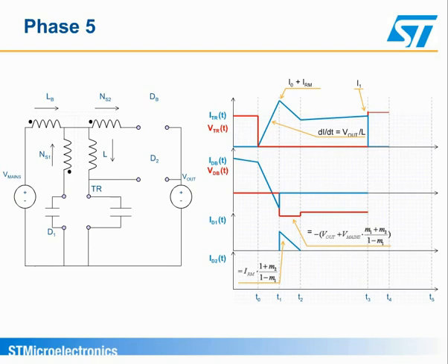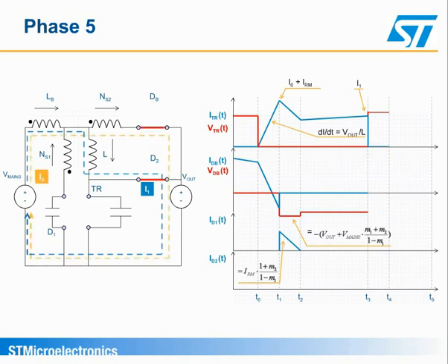The voltage across the capacitor COSS of the transistor increases linearly through the current I1 stored in the inductor L until reaching Vout. From this value, the diode D2 is biased and starts to conduct, bypassing the current I1 stored in the inductor L to supply the load. At the same time, the voltage polarity across the main inductor, LB, changes, and dB starts to conduct as well. At this point, dB and D2 share the current.